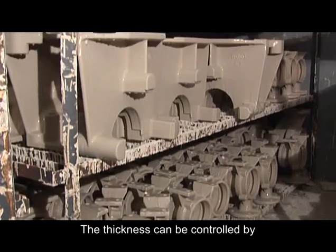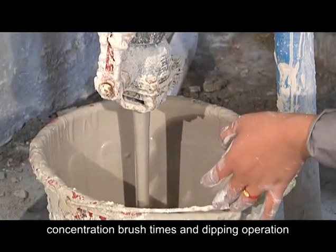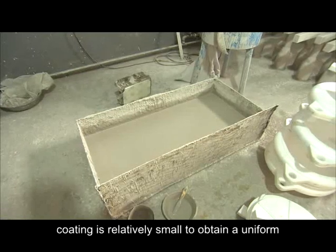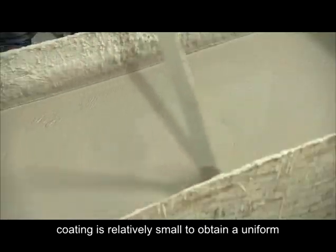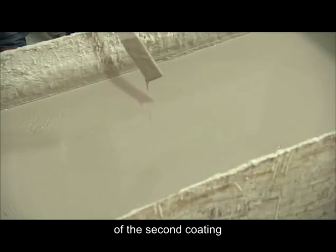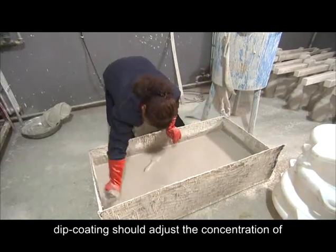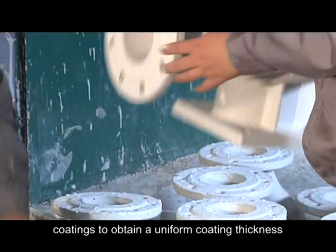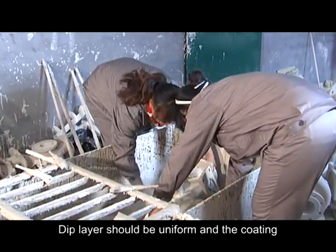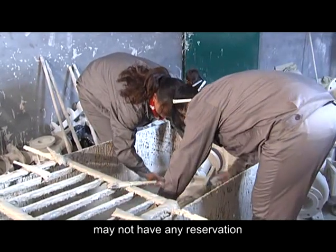The thickness can be controlled by concentration, brush times, and dipping operation. For the first time, the dipping concentration of the coating is relatively small to obtain a uniform thin coating and improve the property of the second coating. For the second or third time, the dipping should adjust the concentration of the coating to obtain a uniform coating thickness. The layer should be uniform and the coating should not have any reservation.